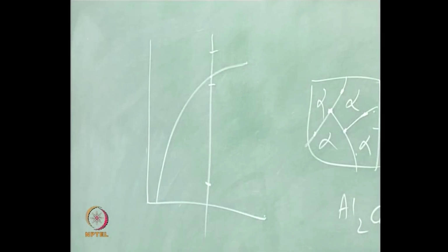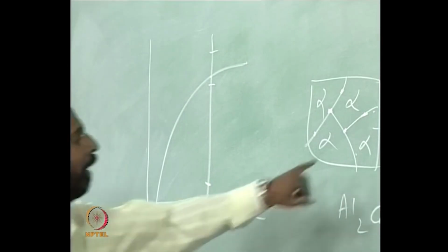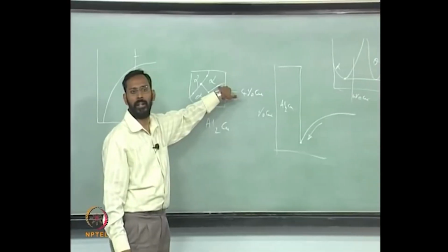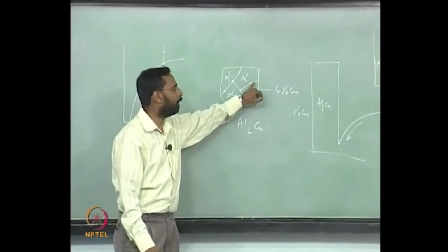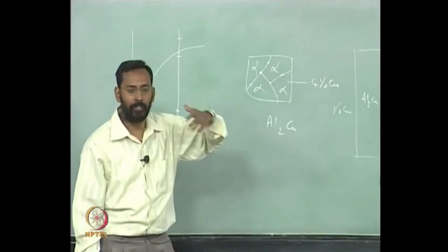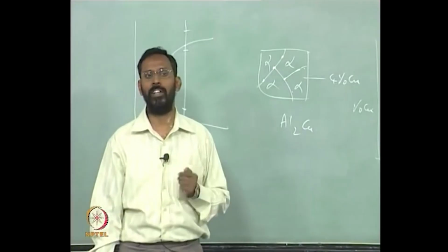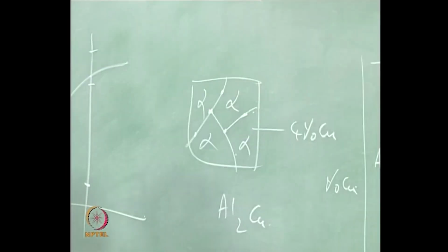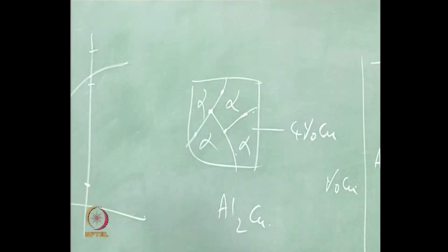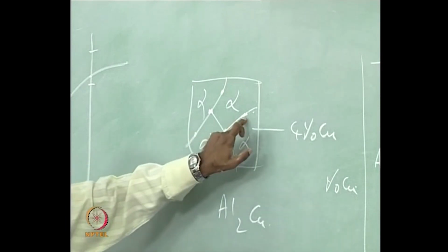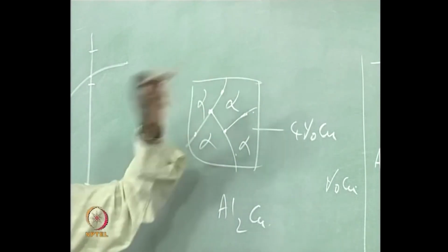Thermal diffusion is more difficult, and nucleation and growth of the theta phase, or any precipitate phase for that matter, is more difficult. In this particular system it is the theta, in some other system some other phase maybe; in this system the equilibrium phase is the theta phase. So, that theta phase to nucleate at the grain boundaries is more difficult.